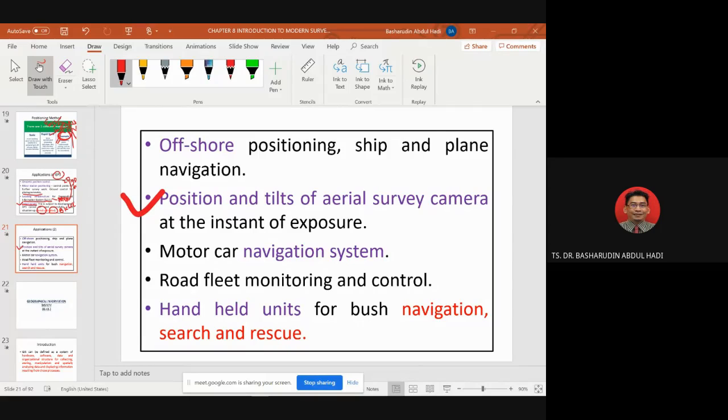Sometimes you can see that an area has another problem. For example, when you go to that place and measure the height using GPS, it is 5 meter. Two months later, you measure using GPS, it goes down to 4 meter, settlement. Then 5 months later, you have another complaint, you go and use GPS, and you can see that the settlement has gone to 3 meter. So you suspect that it is clay, but you don't know.